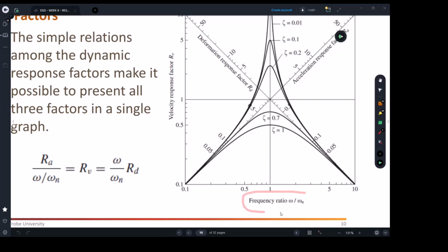say whichever frequency you want to set up your test with. If you ended up with 2, you're going to go all the way up. By the time you hit the curve, the one with the 0.2 ratio, it's going to be somewhere here again. It should be super vertical like that. From here, you can read the displacement, which is about 0.5 of whatever the unit is. I don't think the unit is mentioned in this curve, but remember, this is a ratio, RD, the ratio between dynamic over static, so there is actually no unit.